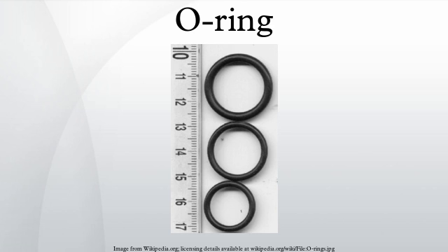The rubber industry has gone through its share of transformation after the accident. Many O-rings now come with batch and cure date coding, as in the medicine industry, to precisely track and control distribution. For aerospace and military defense applications, O-rings are usually individually packaged and labeled with the material, cure date, and batch information. O-rings can, if needed, be recalled off the shelf. Furthermore, O-rings and other seals are routinely batch tested for quality control by the manufacturers, and often undergo QA several more times by the distributor and ultimate end users.